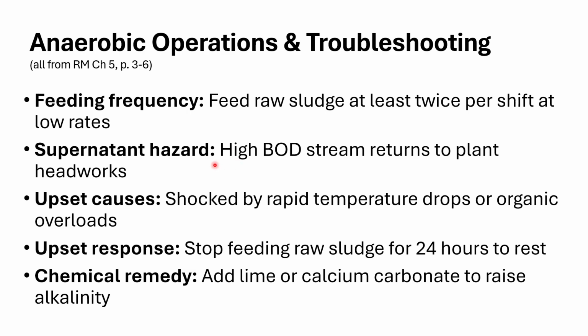Okay. The supernatant, it can also create a hazard. The supernatant, that cleared up liquid that's got the solids removed from it, it now has a high BOD, a high amount of food, a high organic content. It's also got a low dissolved oxygen content. We're going to send that to the plant headworks so that we're going to reprocess it, and we're going to make sure that that BOD feeds our bugs and is treated before we send things out to the secondary clarifier, secondary treatment, and what have you.